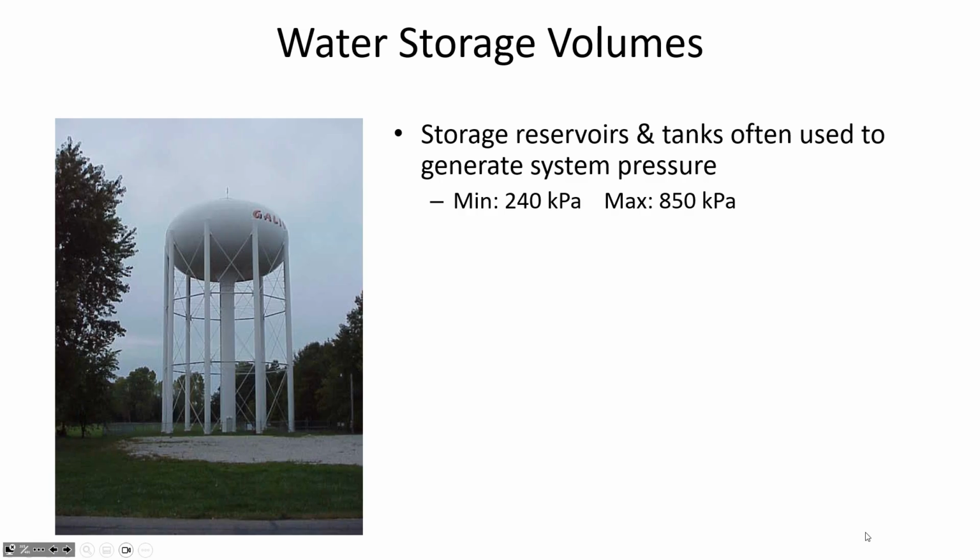In part 3 of the project, we're going to ask the question, how big should the reservoir be? And the purpose of the reservoir is partly to provide pressure to your network. You'll remember from part 2 of your project that how high on the hill you put the reservoir causes the pressure in the network. So if you need more pressure in the network, you move the reservoir higher and higher on the hill.